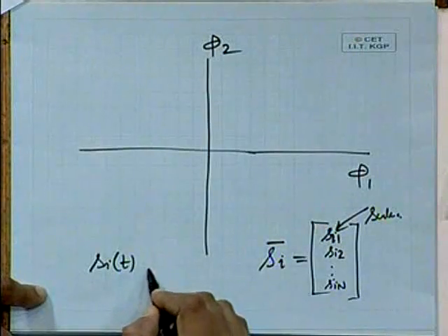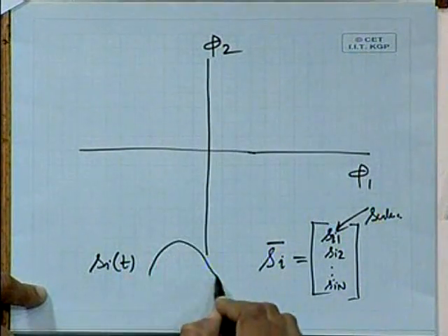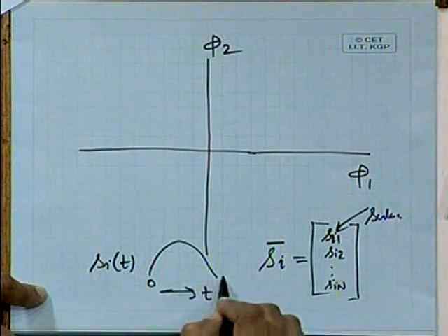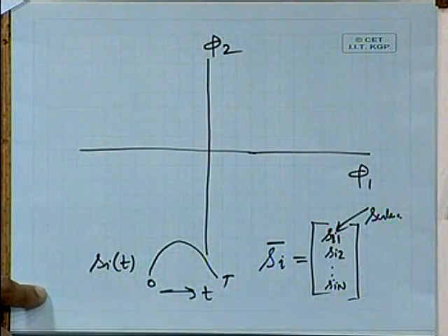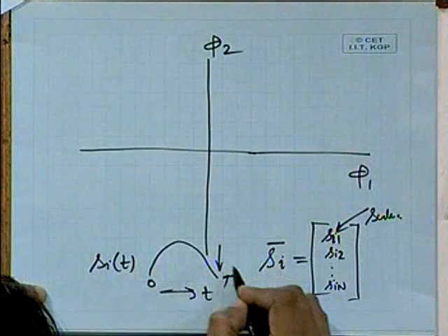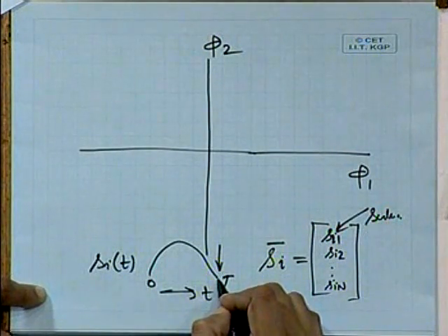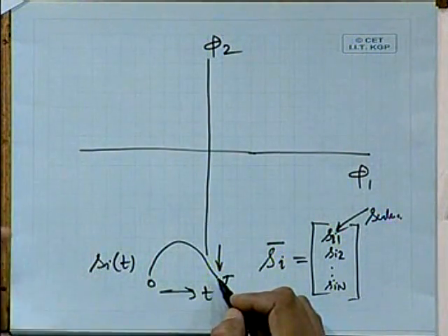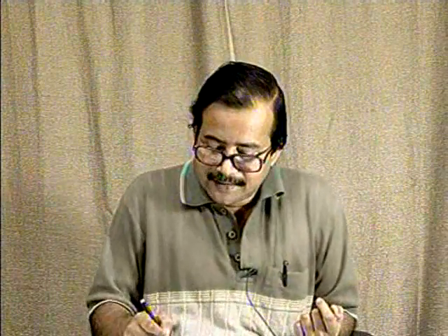Okay, so your Si(t) may be changing with time. Si(t) does change with time, with t, over 0 to capital T. But you come out with the scalar values only after integration. So once the integrated output you have sampled at t equal to capital T, you get these scalars really. So do they have any implication of time if I consider only one symbol? No, and that's what I plotted in the signal space.